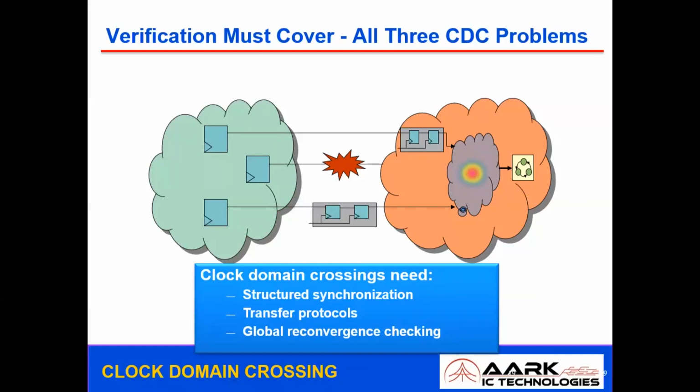So how do we generally follow protocols in communication systems? First, we send a request, and the receiving end receives the request and sends an acknowledgement. Then the transmitting end transfers the data. These are called handshaking signals. You need a proper protocol between two different domains which are operating with two different clocks. If you follow these protocols, then you can avoid data loss.